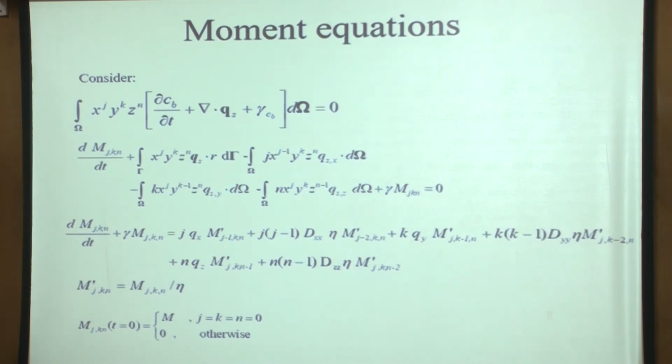So this is what I mean by saying that the extension is the same, but now you have to carry much longer equations along with you. Okay. But whatever we did with one dimension, we are simply now doing it in 3 dimensions. And notice that because these are bulk concentrations, I have m, but in the flux terms we had resident concentrations, we have m prime. In this particular case m prime and m are simply related by the parameter porosity. Okay. So they're all equivalent.